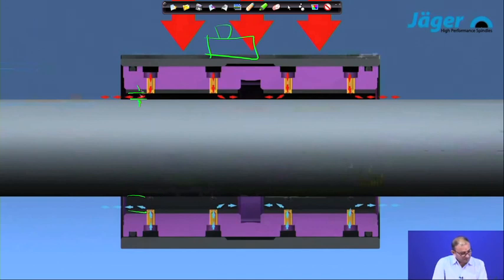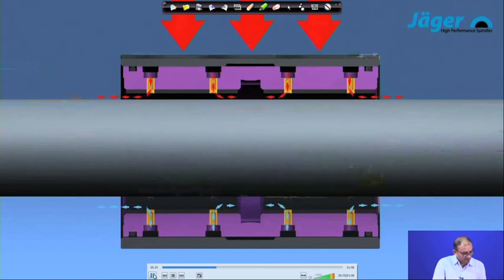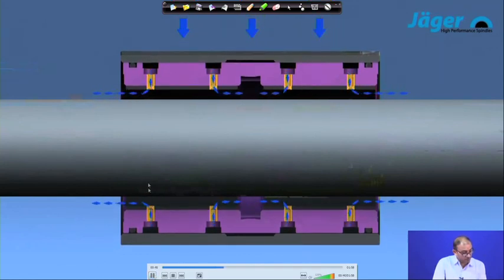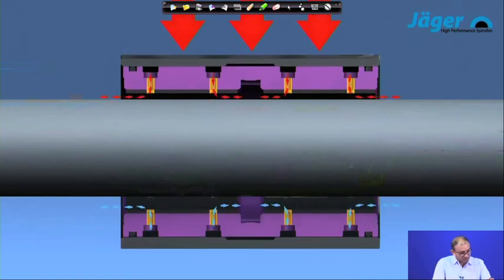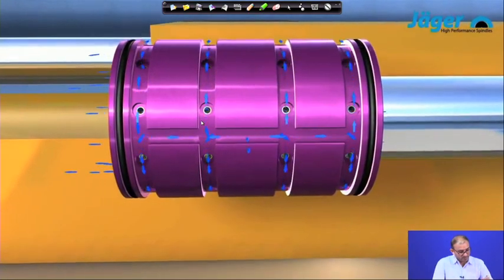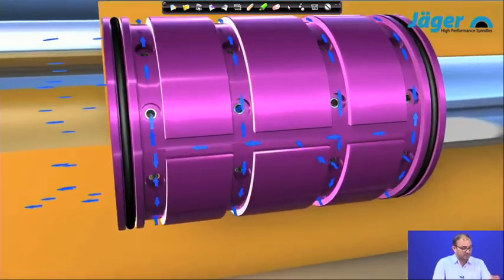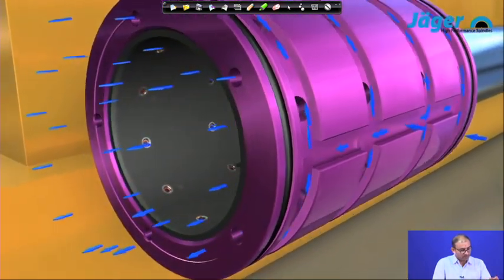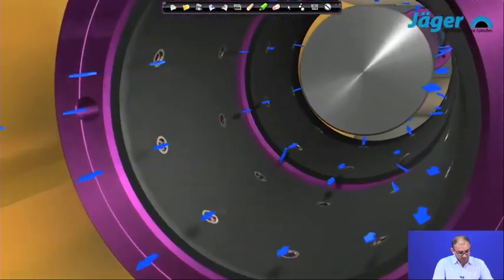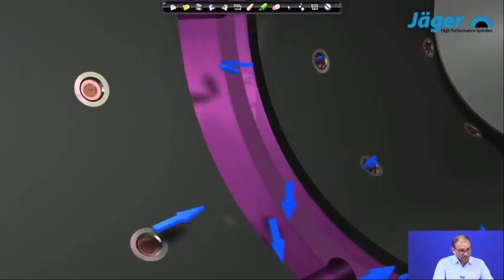So, once this thing happens, at that time this particular bearing will adjust itself. You do not need to see how it is going to happen. Right. So, in this location, this is the red color, that means high pressure, again both things are maintained, now both things are in blue color. Again it will go down, this becomes less high pressure, this is a low pressure zone, again it will match the part. So, in this way what is happening, this is a self adjustment bearing. So, wherever there is a pressure difference, it will maintain that pressure difference by pressure regulator of this particular air bearing. So, this is the way how it is useful.